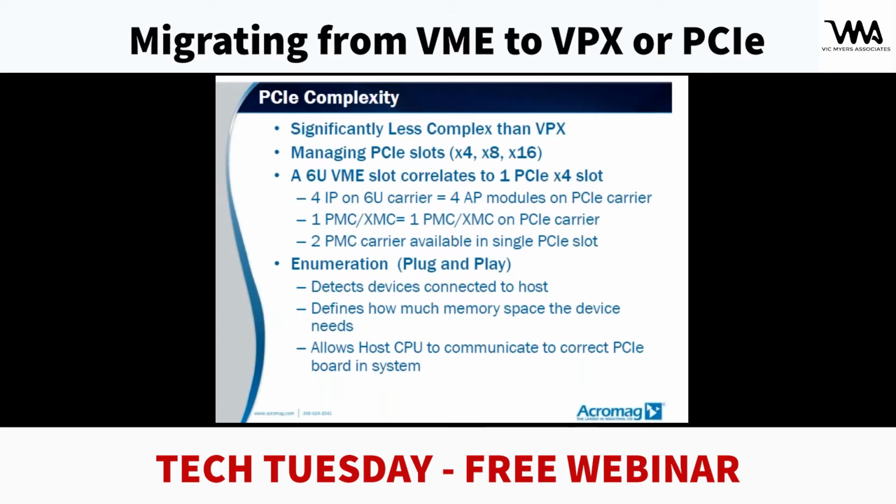So when you look at a GPU card or an FPGA card and you have a by 8 interface running at Gen 3, you have a lot of bandwidth in that single slot. Most oftentimes, your motherboard might have 32 lanes on it, so you might have to break that up into 8 by 4 or some amount of by 8s, 1 by 16. So there is some management there to understand how many PCI Express lanes you have and how you're going to partition that.